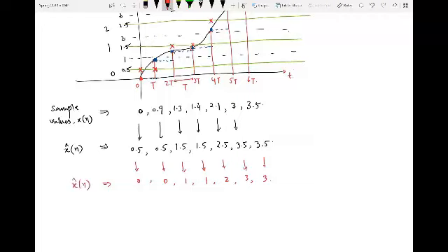You can also describe it in terms of the level index. So you see, we have converted that discrete time sequence requiring infinite precision into a finite number of levels. The output of the quantizer will always have a value from these 4 values: 0, 1, 2 and 3. No matter what the actual value of the sample was, the output of the quantizer will be either 0, 1, 2, or 3.